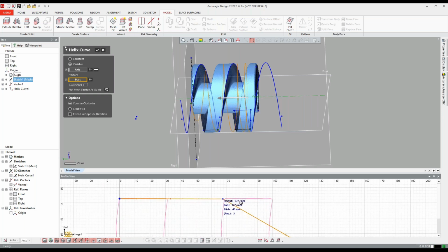This height, we could always adjust. You can click in all these to quickly adjust them, so I don't have to just drag it around. If we came in here and said 68, we can just watch everything move over. So you can poke at stuff to see what you want to do. Height drives a lot of things in here because it is reverse engineering. So we drive a lot from the height and then adjust pitch and revolution from there.